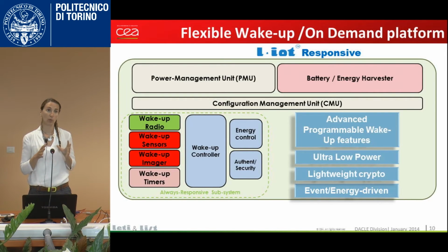For this, we need some control. We have a lot of wake-up sources, and then we need some control. This is done by something that is asynchronous. It means that most of the time, this part is really in sleep mode, and once we have a wake-up interrupt, then the wake-up controller is reacting with the rest of the platform. For this, we also need to have some energy control. This energy control is able to control all the architecture according to the energy needs that we have. And of course, this part is also requiring a lot of security, because you do not want to have some security issue in a wake-up platform.